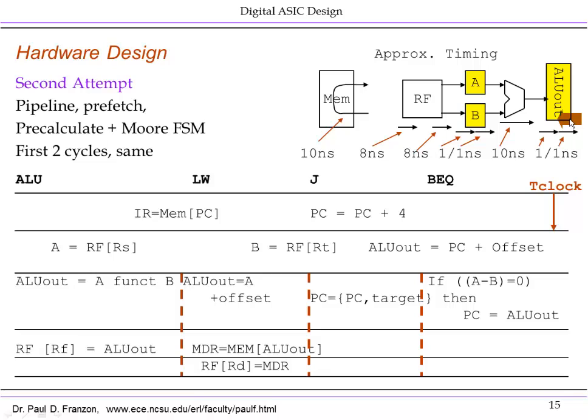And as I said, I'm going to add another register to the output of the ALU, which is called ALU out. So we are adding registers to shorten the critical path. That is really the best way to think about this. We're adding registers to shorten the critical path by breaking it up into a 3 clock cycle critical path. This, of course, means we're going to take more clock cycles to complete our operations.